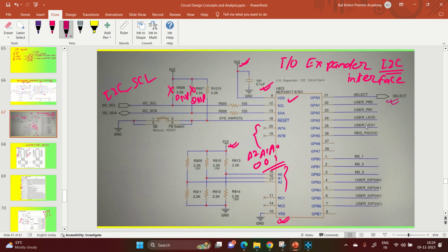Similarly, you can drive some LEDs, LED 0, LED 1. So you can drive them, or the pin can act as a source also, or sink also. I am taking an indication of a power good signal from a regulator. So my regulator is working really fine, and I am taking the status of that. So these are the pins that are acting as IO pins to understand the status of the different parts of the circuits, right?